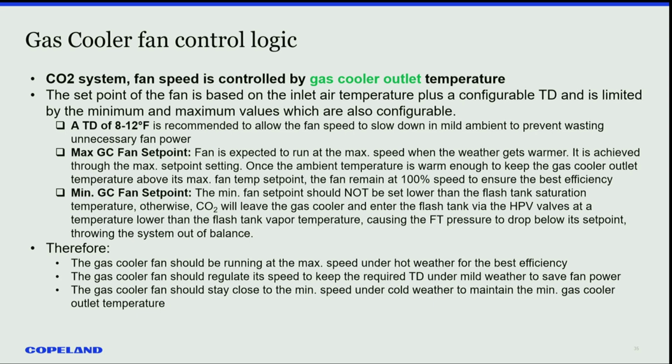The minimum gas cooler set point should not be set lower than the flash tank saturation temperature. So if my saturation pressure is 520 pounds, I sure don't want my gas cooler minimum pressure to be less than 520, because the liquid going in would be so cold that it will mess up all of the liquid going to all of your cases, and then you're going to start having control issues.